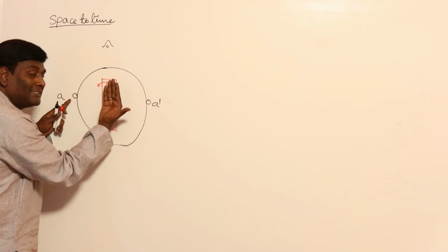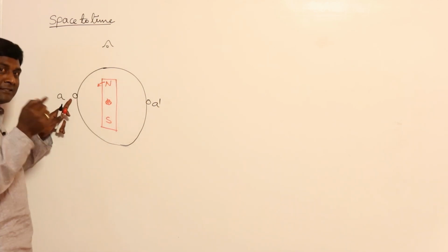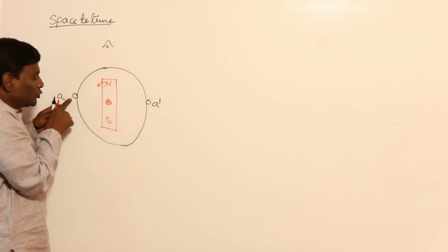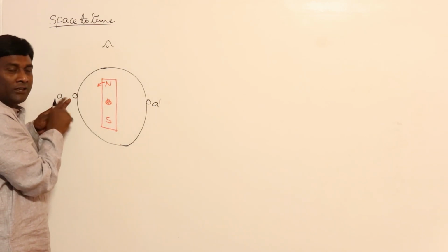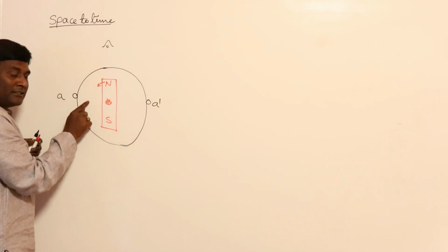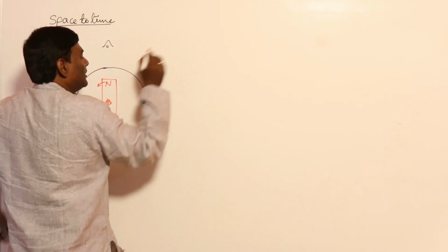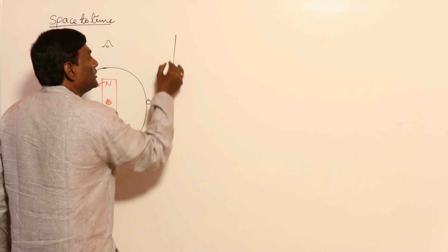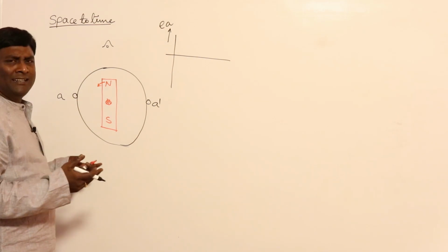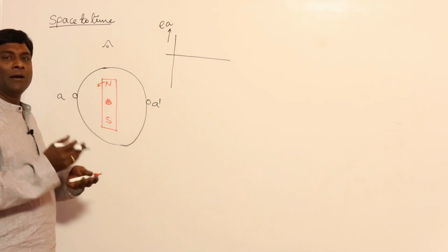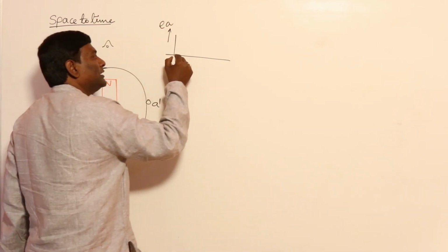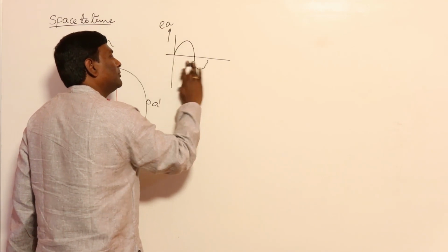Now if I rotate 90 degrees in space, space is the input, the induced voltage will be maximum. As of now the induced voltage is 0; if I rotate this by 90 degrees, the induced voltage is going to be maximum. For example, let me draw the induced voltage in conductor A. I am assuming the ideal case, in the sense that the flux density distribution of the pole is sinusoidal. As of now induced voltage is 0, after 90 degrees it is going to be maximum, so the sinusoidal induced voltage will be like this.